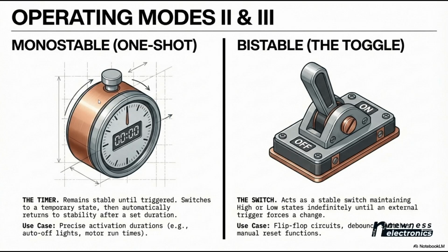On or off. Now, if you remember, there was this temperature controlled fan circuit that we made earlier that was coming on gradually. You can use a 555 IC to cut off that gradual turning on approach. So with 555, you can ensure that it's either fully on or fully off once the trigger is applied. Do you see that?